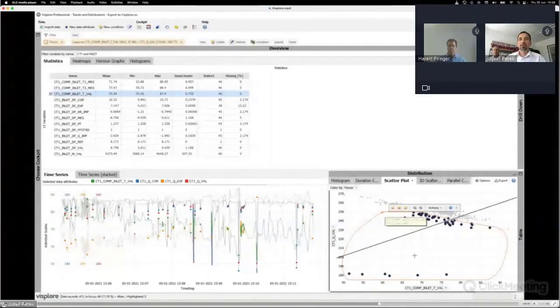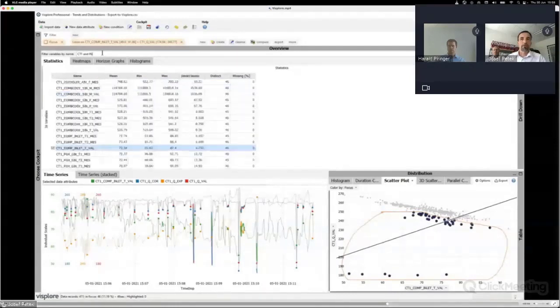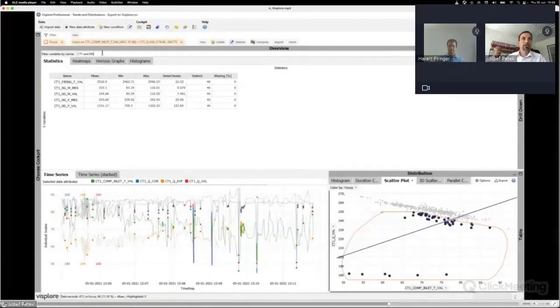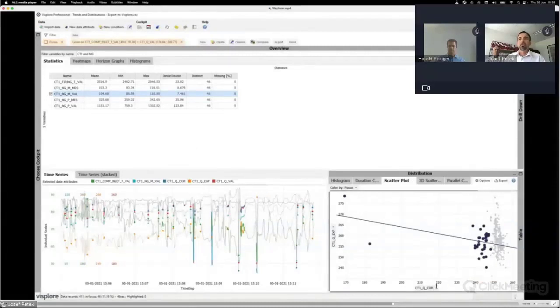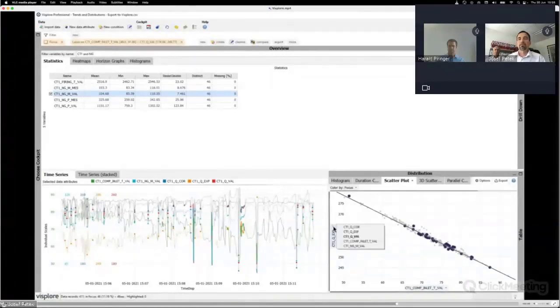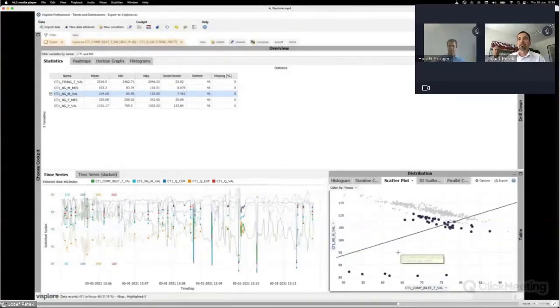And once we made that selection, the target is to find other parameters that would help us explain the reason for the situation we see here. Other parameters related to gas turbine operation, one that quickly comes to mind is the gas turbine fuel flow. So I select gas turbine fuel flow here, and in essence I do the same. I plot fuel flow, this time against inlet temperature, and what we see is a very similar behavior compared to what we saw before on the power,